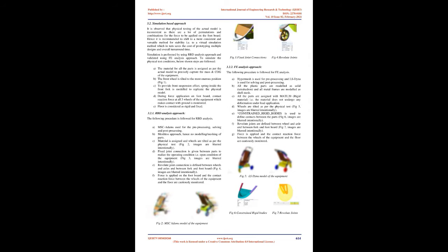Test setup. The physical test procedure is carried out as per the standard prescribed by the concerned authorities for respective types of three-wheeled equipment. The physical test is performed as described below. The equipment is placed in the manufacturer's recommended use position with all wheels on a flat horizontal plane. With no external weight on the equipment, the footboard is placed in the lowest use position. The test is performed with the wheels positioned to most onerous position, Fig 1, which is decided upon after averaging several test data.